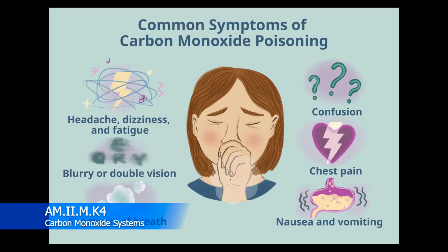So now that we know something about the types of fires that could happen on aircraft and the different fire zones, let's talk about another killer that is not really talked about as much as fire itself, but something you're going to have to prep for. Anytime you do an aircraft annual, you're going to change out a carbon monoxide filter or detector, and it's something that absolutely can kill people on a regular basis because it's very hard to detect without some sort of indicator inside the cockpit.